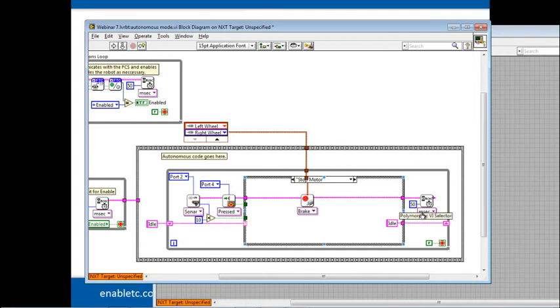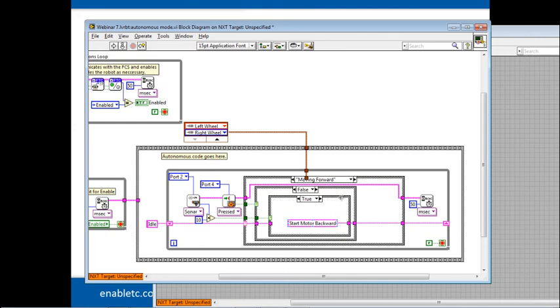So for those of you who have been familiar with programming in LabVIEW for Tetrix in previous years, there's a watchdog timer function. NI has simplified the usage of the watchdog by embedding it directly within the wait. So by using the wait, we can make sure that that watchdog timer is hit if we're going to be sitting in either our moving forward or our moving backward states where nothing's happening. So I strongly suggest you give this code a try. You're going to find quite positively, I hope, that the system is really responsive as opposed to the state diagram and the state machine that we implemented last week, which always caused at least a 1-second delay before anything would happen. This system is responding within 50 milliseconds to your ultrasonic detector and your touch sensor.